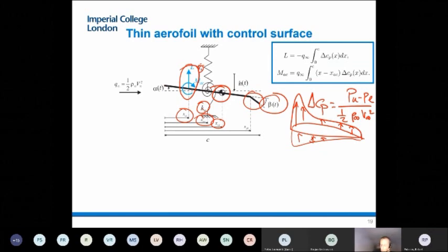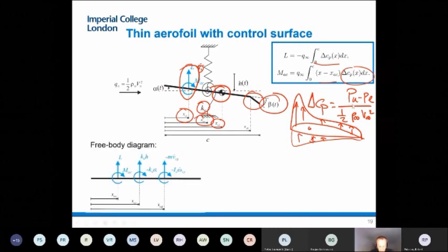And then what I will do is integrate those pressures to obtain the lift, or integrate those pressures times a distance to the reference point to obtain those moments. Okay, those are the ones I said before we obtain empirically. What I will need very soon is models to compute those. So once I have that, the next thing I will do is to say, well, what are the equations of equilibrium? And you can use any of the methods that you have at your disposal.